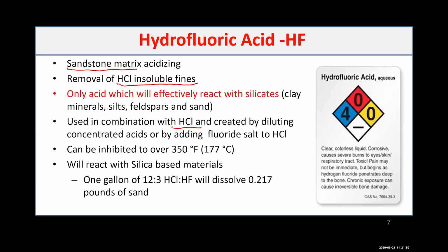One of the other concerns, as you can see from the diamond, the SDS, or the characteristics of HF, it has a health rating of 4. This is one of the nasty chemicals that you will have on location. So you don't want to breathe it or touch it or anything. So from a health point of view, that's not a good chemical to be around.